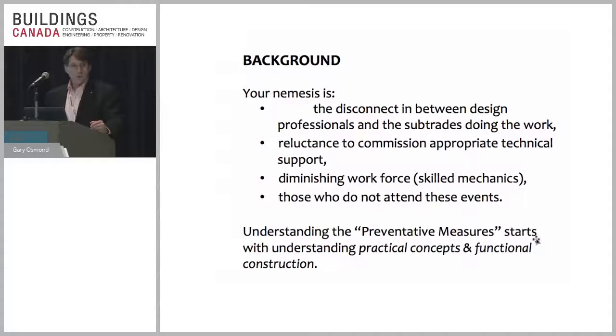It's not a science term, it's a pretty good one. It's called, do you have the wherewithal? Do we have the wherewithal that in the design phase, and more importantly in the construction phase, that everybody understands what's going on? We can insulate buildings, but functionally, if it's not properly insulated, you're going to have condensation problems. We can put up water-resistant barriers, but if they're in the wrong plane of the insulation, you have a problem. So everybody at the table has to understand the functional concepts of the way buildings perform.